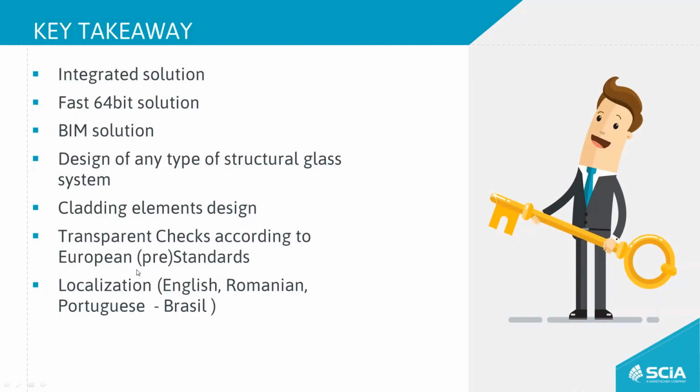And I think this is very important when we discuss about glass, and you need to go to a checker or to an insurer to make sure that everything is according to a code and everything is transparent. So my idea is to make the software so that it's not a black box. It shows exactly as if somebody did the calculation on paper, but at the same time we model it with finite elements, so we know exactly what happens in any bit of the glass.